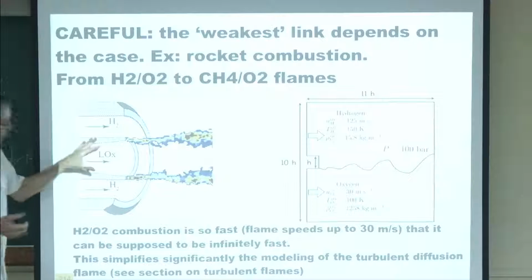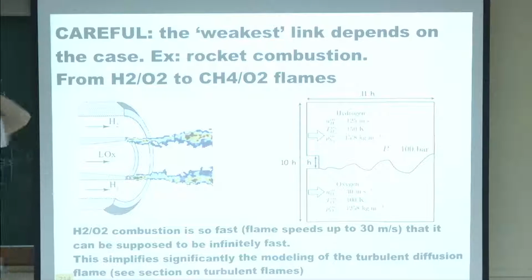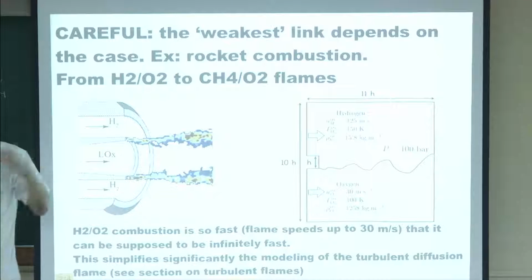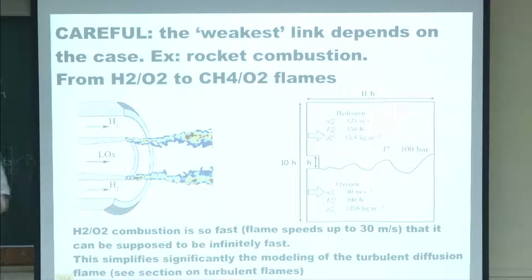That's an injector of the Ariane engine, the H2/O2 engine. So we inject cryogenic oxygen, so it's a supercritical state, if you want, very high pressure, and hydrogen on that side. In the main engine, there are 300 injectors like this. So it's a very complicated flow.